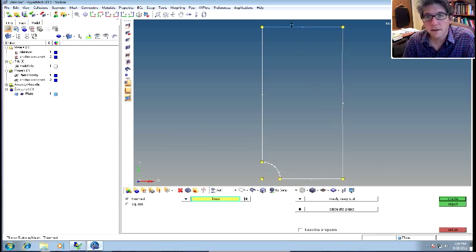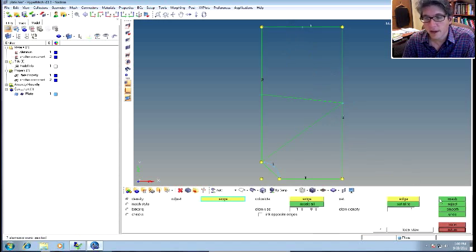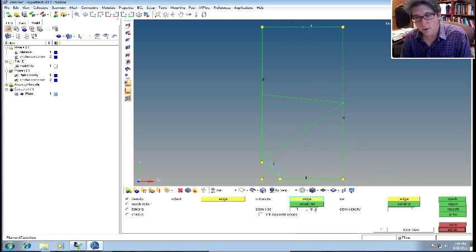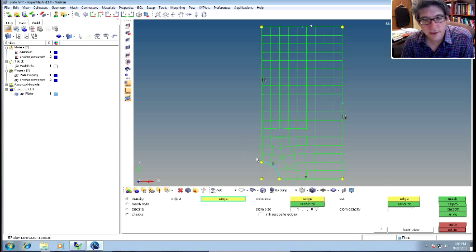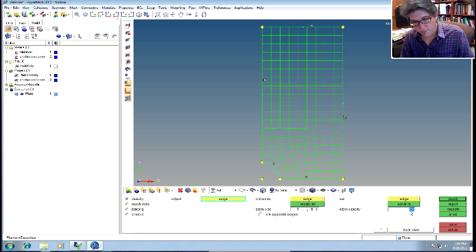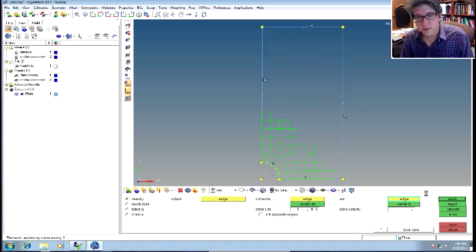and then we hit create. So it makes the very coarse mesh. Let's get the size to be about 1. We recalculate all, so there's the mesh for that one. Now if I wanted to bump this up, it looks like they got rid of that option. You used to be able to toggle and add more nodes here, but okay. That was set to 3. Let's make this more like 5, and I'm going to set this edge to be 5. So now it has 5 nodes here. You can see how that mesh will look. It added some more elements on here.